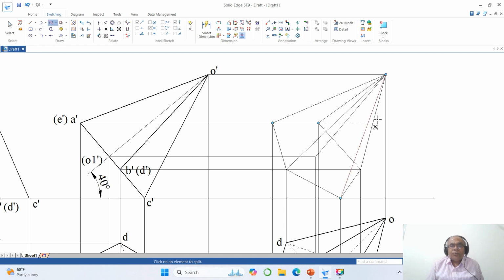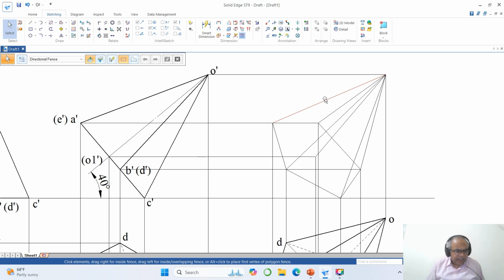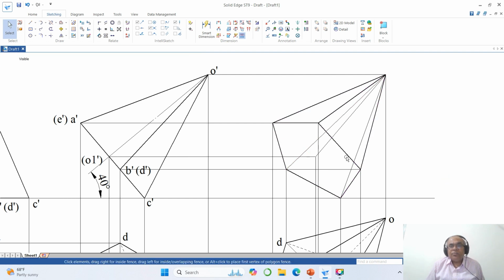Okay. Now you apply all the boundary conditions. All the exterior edges of the boundaries of the solids are visible and the surface nearer to the observer and this line will automatically become visible. Once you do that, these two become invisible edges. So go to hidden edges and make it 0.35 and this is going to be the axis line.